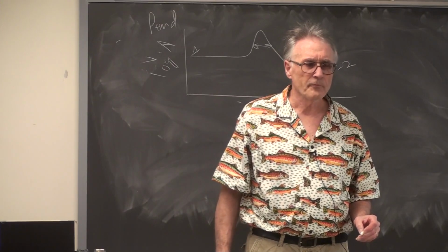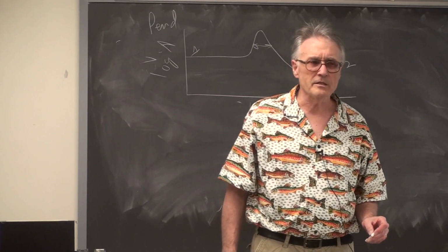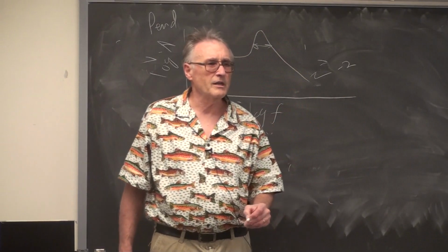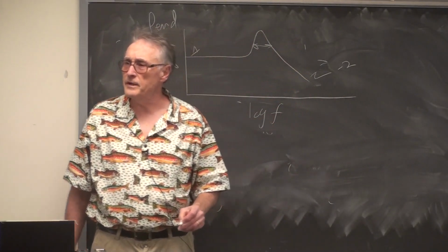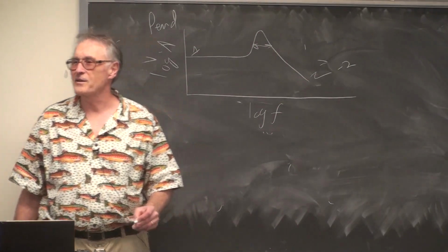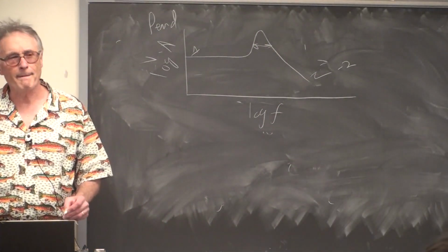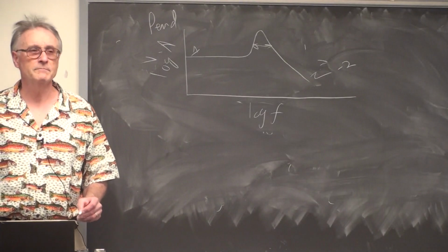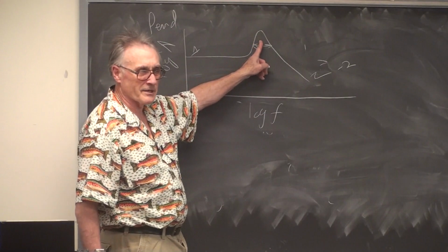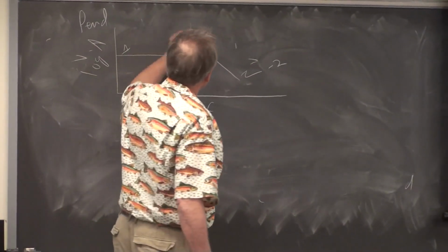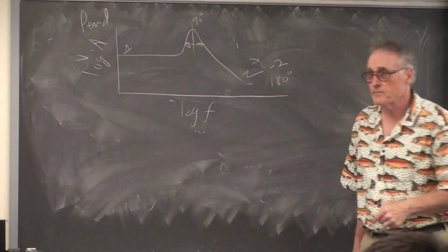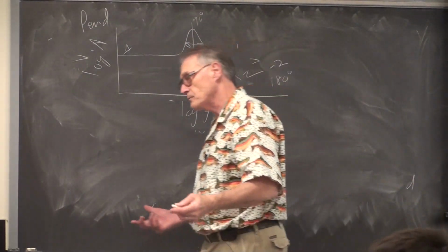Do you remember, for a minimum phase system, a slope of -2, what that implies? Minus 40 dB per decade. What is the phase shift? Do you remember that? 180 degrees. The phase shift of a second order resonance system is 90 degrees at resonance, 180 degrees at high frequencies.